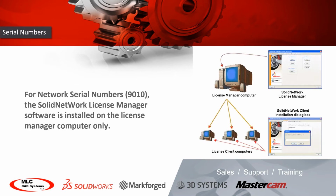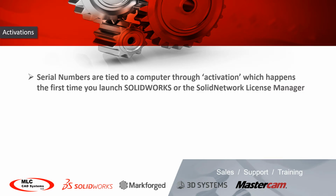Keep in mind, if you're using a 9010 number, that network serial number, this network license manager only needs to be installed on one machine. That one machine is the one that gets activated, and then it distributes license to clients across the network. Talk a little bit more about activations. Serial numbers are generally tied to a computer through activation the first time you launch SolidWorks after installing.